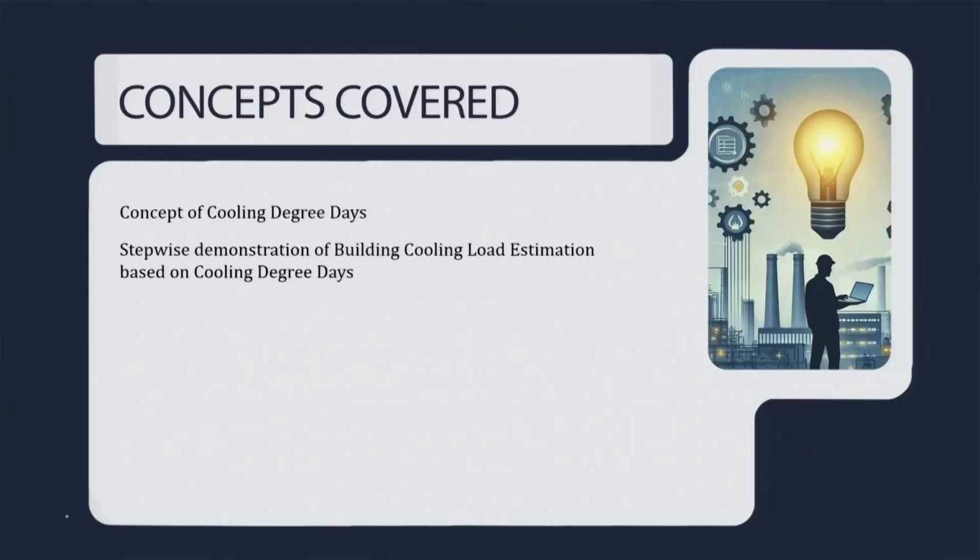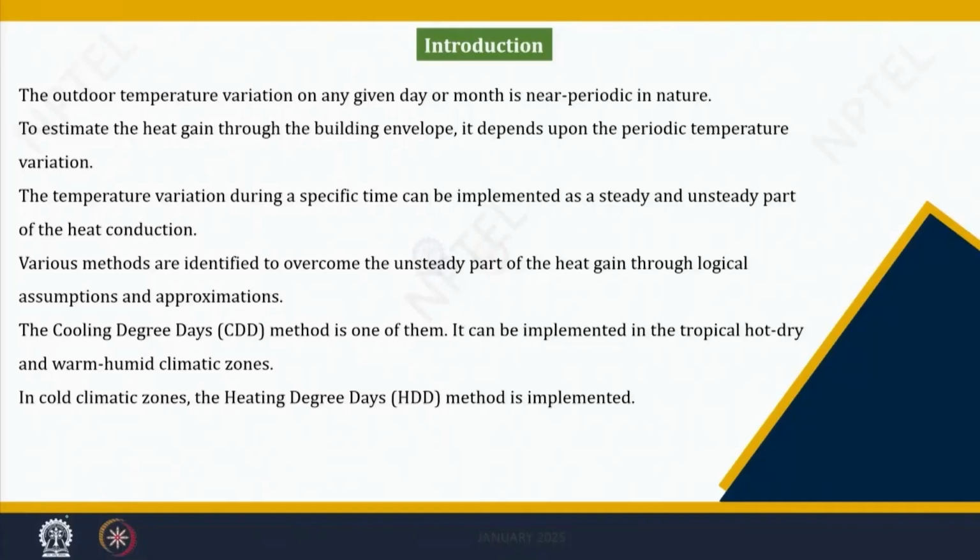In this particular discussion, we will cover the concept of the cooling degree days, and we will discuss stepwise and give a demonstration on how, through the cooling degree days, the building cooling load can be estimated. Now, first of all, we need to know what is cooling degree days and what is heating degree days.